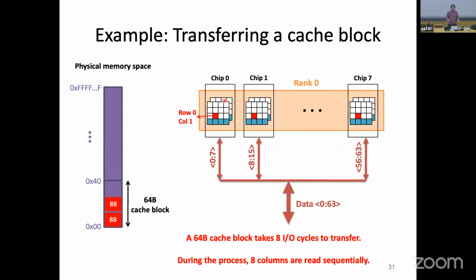We refer to this operation as a data transfer burst. Basically, you send a single read command, but you receive data in a burst of 8 data transfers in this example. Why does this happen? Because you couldn't have a larger bus to do this operation in a single cycle, because you are pin limited, pins are expensive.